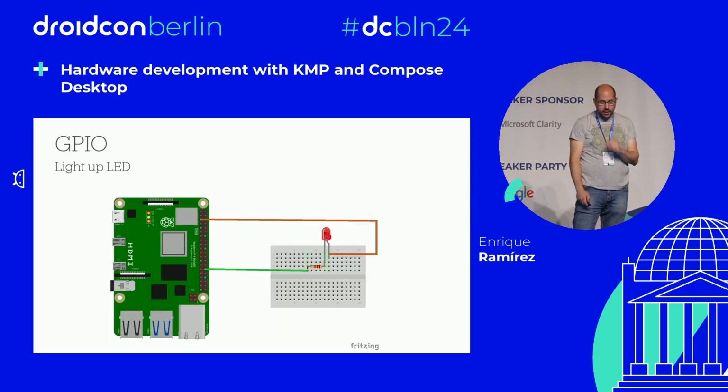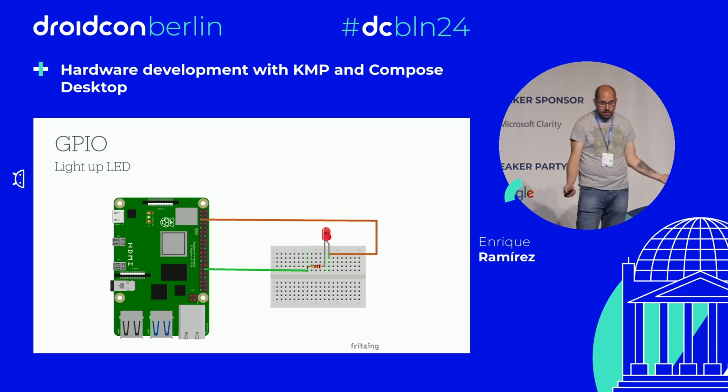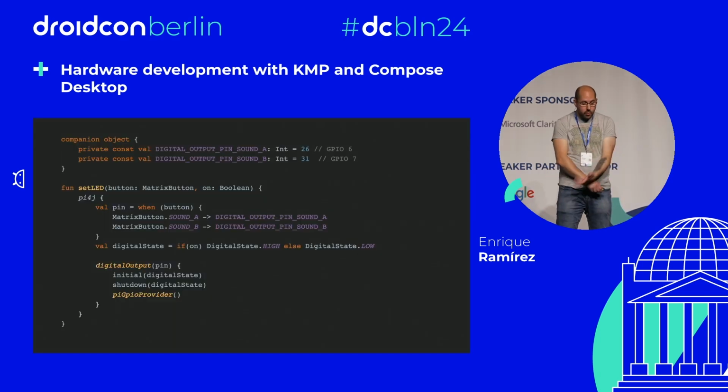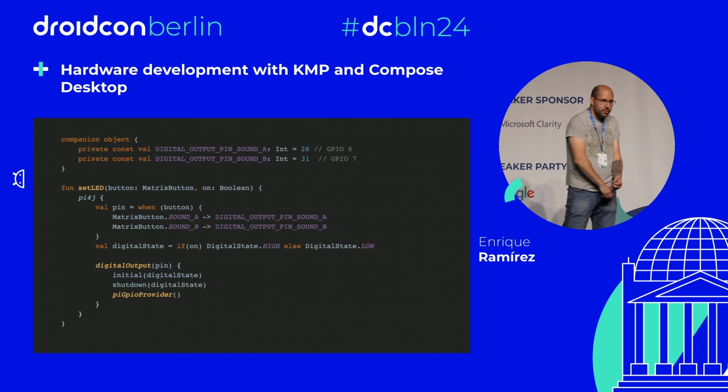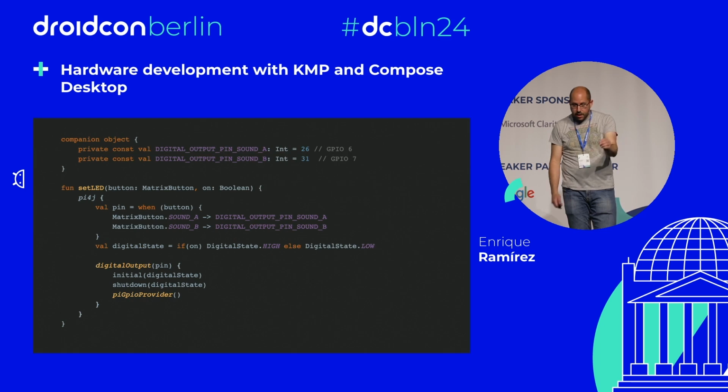Also, the other thing that we want to do is, when you select one effect, you want to know which one is selected. So we could add an LED. Same thing with the GPIOs, but this time we set them as outputs. So now these pins are going to be outputs. And same kind of thing, you need the number of the pin, and you set a state.